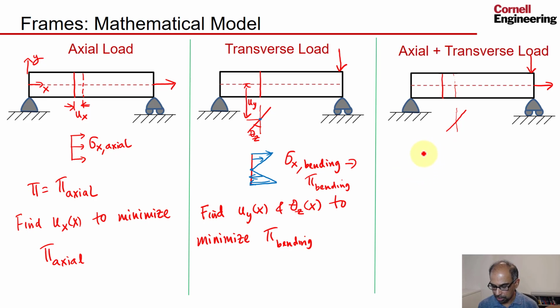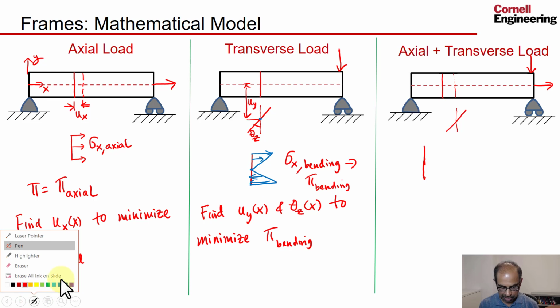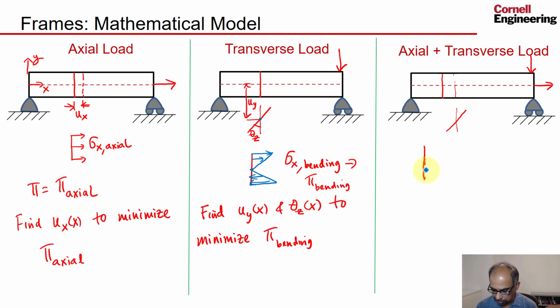So if I look at the stress distribution, pardon me, my tablet is acting up. I just add these two. So the constant plus the linearly varying, and I'll see something like this. So my 0 will move down, let's say, and so in this part of the cross section it's tensile, and this part it's compressive.